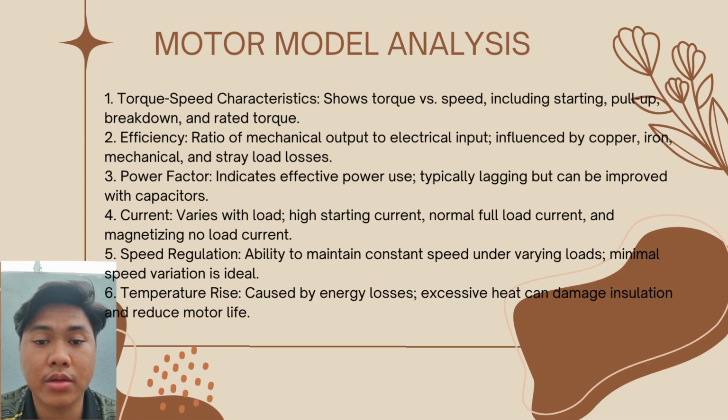I'll be explaining the motor model analysis. The performance analysis of a three-phase induction motor involves understanding key characteristics such as torque-speed dynamics, efficiency, power factor, current variations, speed regulation, and temperature rise. The torque-speed relationship highlights how torque changes at various speeds, including starting and breakdown points. Efficiency measures the ratio of mechanical output to electrical input, with higher efficiency indicating fewer energy losses. Power factor shows how effectively the motor uses electric power and can be improved with capacitors.